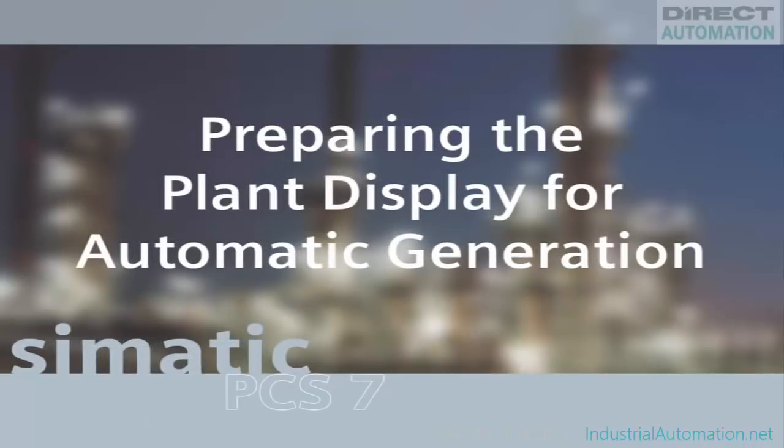In this sequence, we're going to show you how SIMATIC PCS7 automatically populates process graphics with symbols which are pre-linked to function blocks in the controller configuration. Based on the controller configuration, PCS7 can automatically create symbols which allow the operator to control and monitor CFC and SFC charts from process pictures. These block symbols are automatically linked to their associated faceplates. Generation of these block symbols and the process for linking a symbol to a faceplate can be executed on demand.